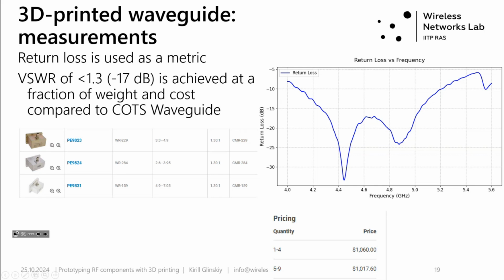Yes, yes. While the waveguides cover, in fact, they have overlapping frequencies. However, if we want to use the waveguide as a boundary condition, yes, those that are on the market will not fit. And there are two solutions out of this. The first solution is to manufacture a smaller or larger RIS cell which fits the waveguide of this lineup. That's the easy way, the coward's way, and a lot of people do that. But we have chosen to use the hard way and measure the cell itself, and therefore we manufactured our own waveguide for this purpose.